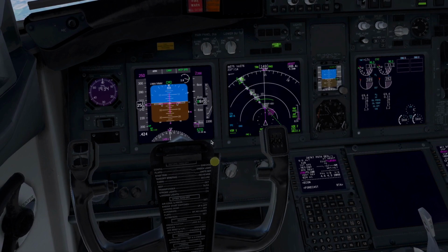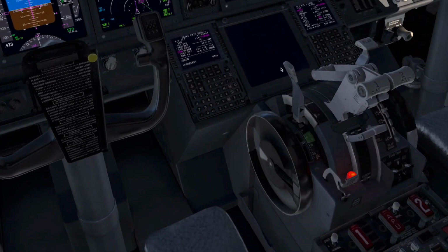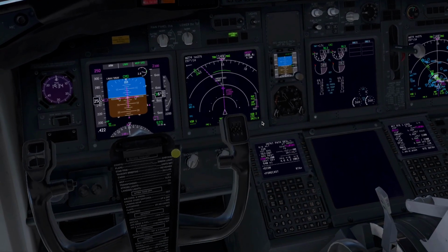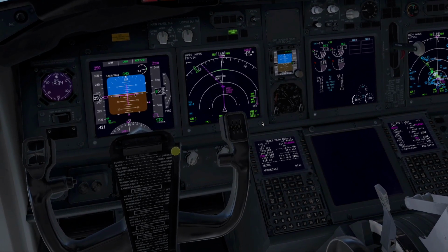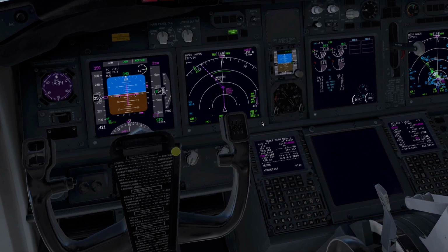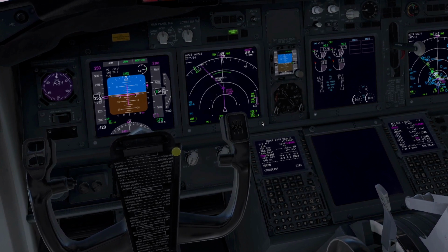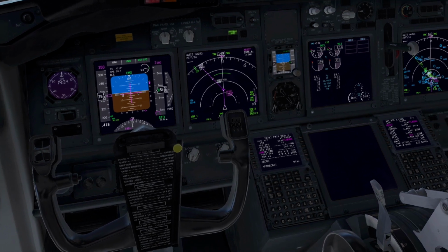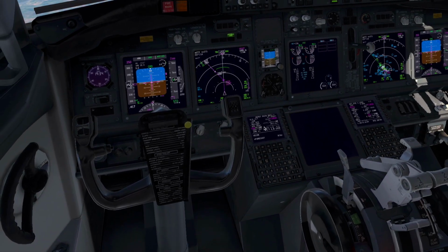Now, as you can see, we're getting closer to the localizer. We're 5 miles out. Ideally, we should be right now at least flaps 5 to intercept the localizer. However, right now it's not possible. We're still fast and high. We want to keep descending, but we don't want to overshoot the localizer with our high airspeed.